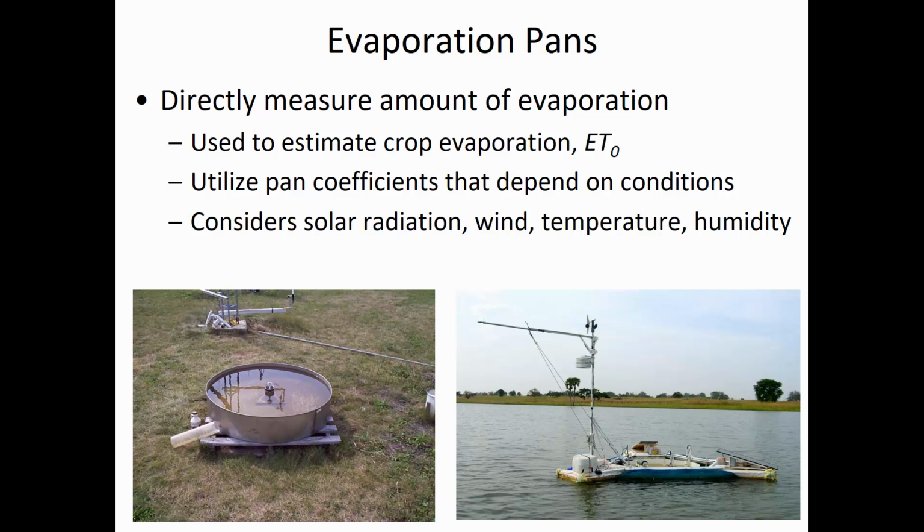That's the transpiration. And so the way it works is that there is a certain amount of water that's put into a pan, and then over time you measure how much the water level goes down from the pan. And of course, if it rained during that period, you'd find the net difference between how much water came in and what the water level change was.